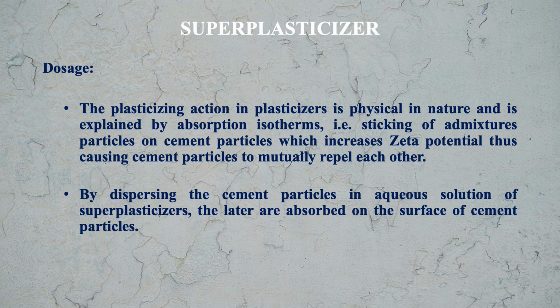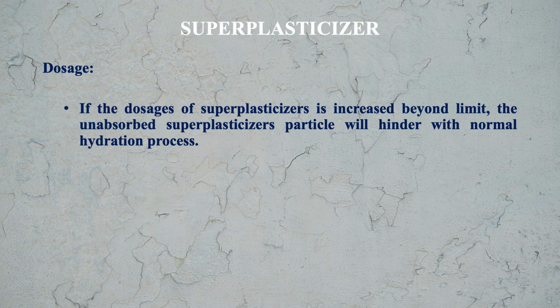By dispersing the cement particles in aqueous solution of superplasticizers, the latter are absorbed on the surface of cement particles. Latter here means the particles of superplasticizers. If the dosage of superplasticizers is increased beyond limit, the unabsorbed superplasticizer particles will hinder the normal hydration process. So this is the problem if we are increasing the dosage beyond certain limit.